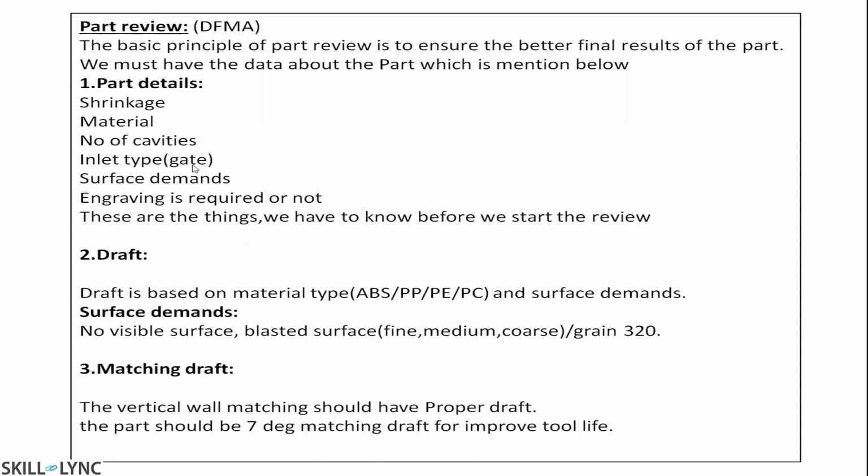For some parts, if you see the laptop board, some areas will be rough and some areas will have a very smooth finish. It all depends on the application, how the plastic is going to be used. It's a visible part. These surface demands will be achieved through the mold. There will be sandpaper and oil stones. That kind of thing we need to clarify from the customers. And what kind of engraving is required?